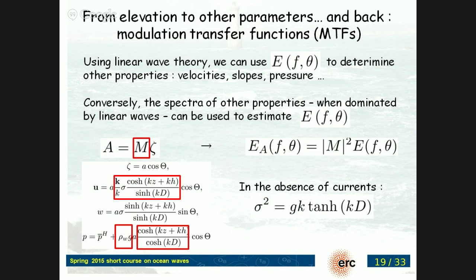The reason why I'm insisting on this is that a lot of people are computing bottom properties from just the wave height, the peak period, or some other funny parameter, which can give you a property, but if you have a funny spectral shape, you will never get exactly what you want. So if you really want bottom stuff, you have to do it this way. And actually, this RMS bottom orbital velocity is one of the output variables of WaveWatch. So instead of working with HS and TP, you'd better use just the orbital velocity coming out of WaveWatch. This is what I wanted to say.